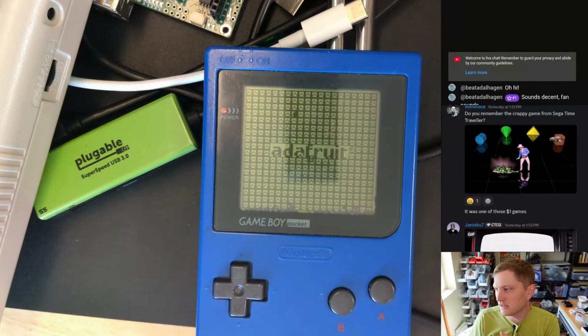The memory in the Game Boy that's related to the display, you can only modify for 1.1 milliseconds after VBlank. So what the GBIO module is doing is storing two command buffers, one for priority VBlank stuff, and one for stuff that's not critical for VBlank. It does the priority stuff, then the non-priority stuff, and then exits VBlank. It should halt and then wait for the next VBlank.